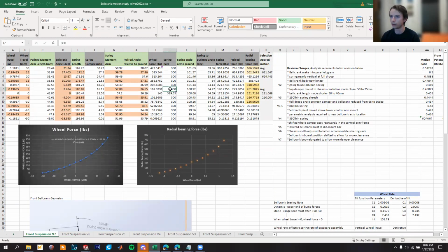Yeah, so our spring rate that was calculated from our guesstimated wheel force was like 330 pounds. So say if our car ends up weighing 700 pounds, we have a 50-50 weight distribution. That's 350 pounds on the front, so that would be 175 pounds on each front tire, and that changes to 397. So due to the availability of these Öhlins springs, I'm simply looking for a spring that's in between 300 and 400 pounds force, because they're not all available.